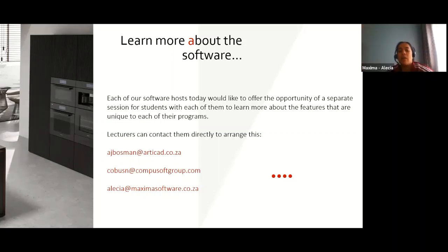Karen, I'd have to say, while it's not considered illegal to have a distribution board installed within a cupboard, they'd still need to comply with the SANS. I think it's 101, the fundamental requirements, etc. But I suggest the kitchen manufacturer or the installer get something in writing from the client, or actually draft the letter and have the client sign it, saying they've been advised that this shouldn't be done.